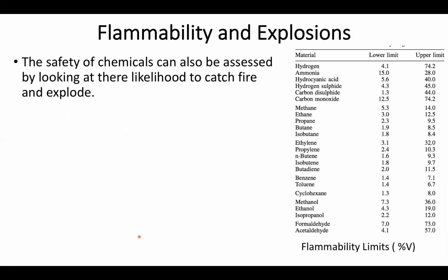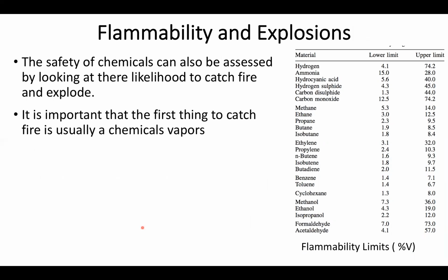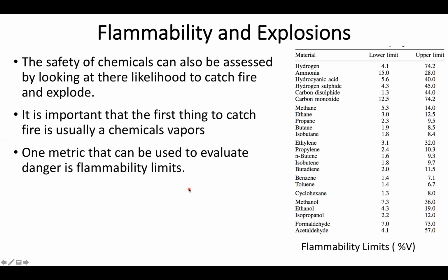The first of which is that liquids almost never catch fire. What catches fire is the vapors above the liquid. So when we're talking about flammability, we really need to focus on chemical vapors. This may be directly above the liquid, or it may be in the wider room. So if I'm evaluating how likely something is to catch on fire, what I need to actually be looking at is the concentration of that flammable gas in the atmosphere.